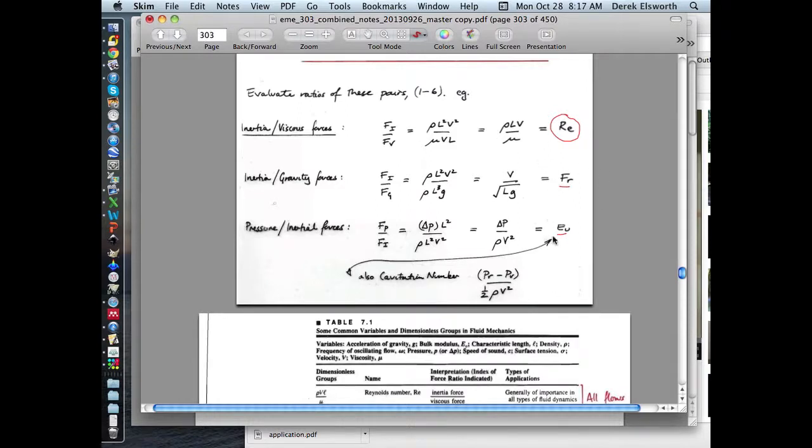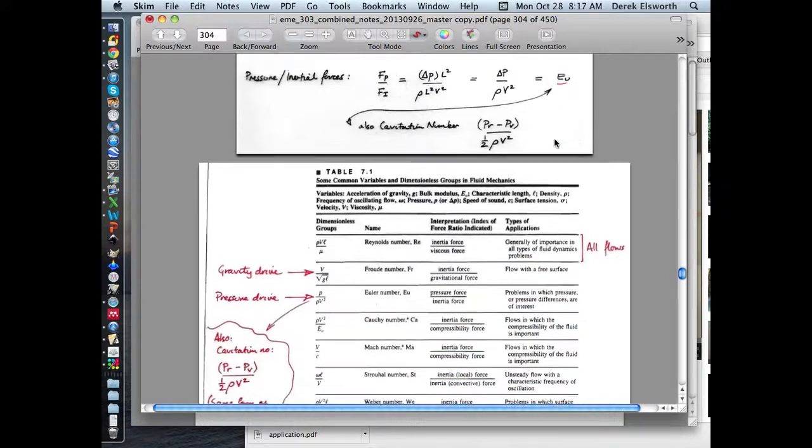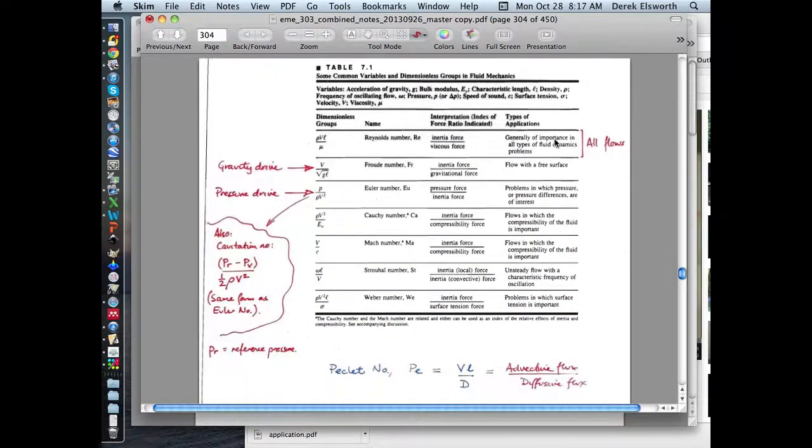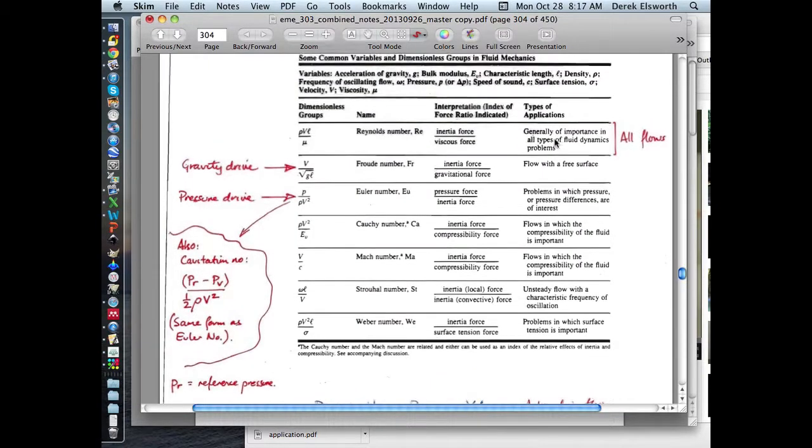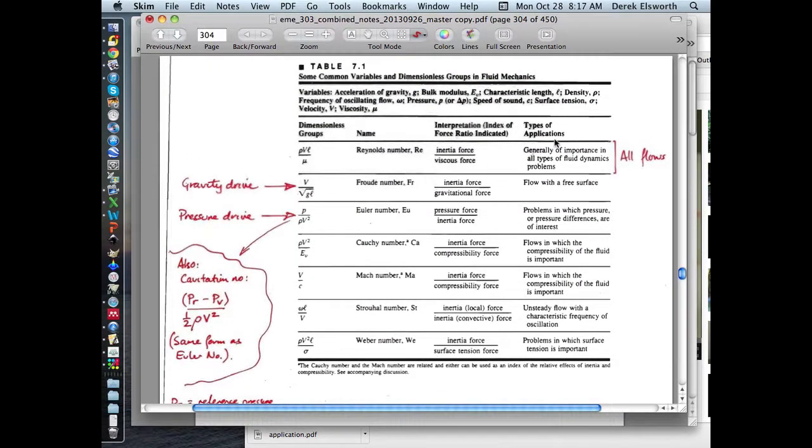So if you are doing things by Buckingham Pi, you should probably hope that your numbers come out to look like these typical relationships. Okay. What else? There are a variety of these different non-dimensional numbers, very important because they govern the behaviors we're talking about. This is a table from your book. We've talked about the all-important one, by far the most important, which is Reynolds number. Secondary are Froude number and Euler number, for the reasons that we've talked about.